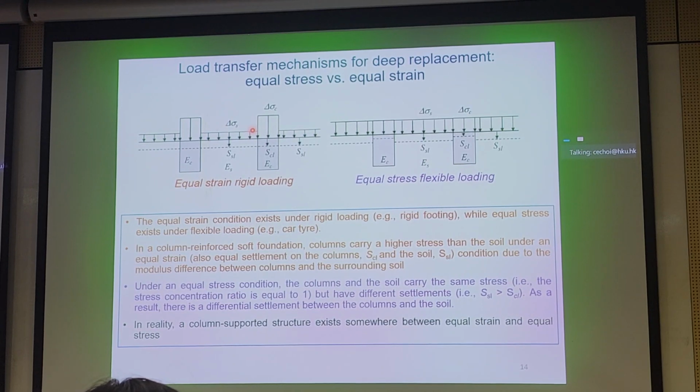If you just want to use this parcel of land for maybe a runway, for example, you want to have nice uniform distributed loading, equal strain is probably quite important, right? You don't want any settlement or differential settlement for a runway. Now, how do you control this? Well, you can control this using a few parameters as a geotechnical engineer.